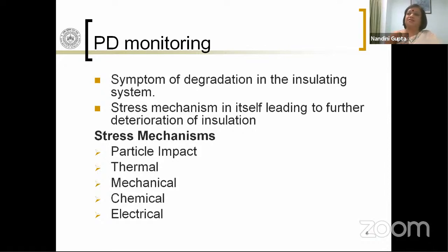So we have the same situation. PD is a diagnostic tool, but if you have a large amount of PD, you want to figure out what is causing the PD, and you might want to stop that right away before something catastrophic happens. So PD can behave as a damaging mechanism in the further deterioration of the insulation. And if PD happens, you already know something is wrong, and you might also want to take action.